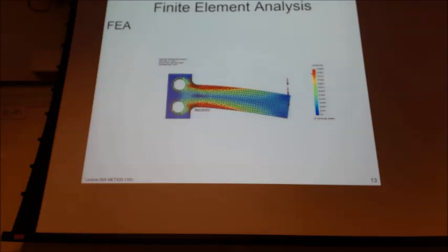For the boundary conditions, we're assuming that the initial state of the boundary condition is the same as it is after we apply the full load. So as long as there's not too much movement there, we're okay. Where you would get out of the linear range is if you have a component that is maybe not touching some other component, and after you apply the load, it begins to touch that other component.